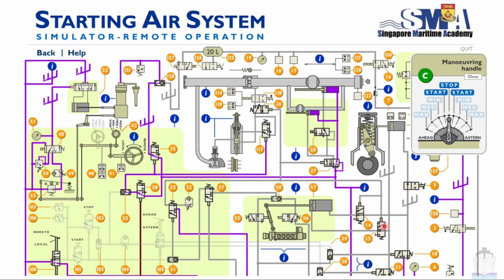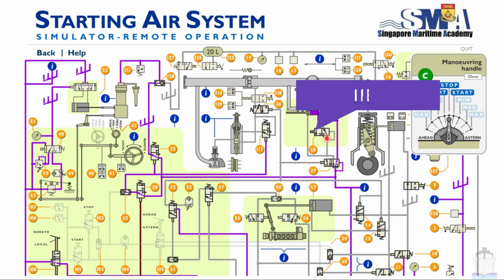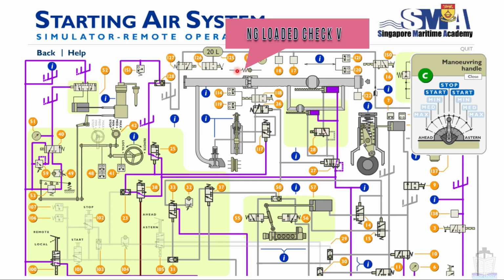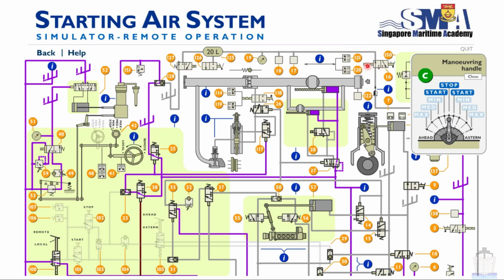3/2A valve, this is also a pneumatic valve, this is detent, this is a quick releasing valve, this is an electrical operated valve, you can see the electrical line is given, this is also having a quick release function, this is a spring loaded check valve, this is a manual valve with detent, this is a check choke valve or shuttle valve.